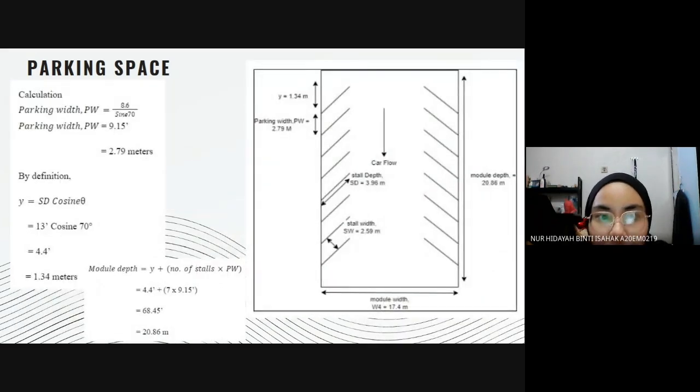Next, for the layout, the parking lot is designed with a double loaded layout, meaning that parking spots are arranged on both sides of a central aisle. This configuration enhances space efficiency by allowing more cars to be parked within a given area. The central aisle is wide enough to allow two-way traffic, ensuring that cars can enter and exit without difficulty. The total number of parking stalls is 7, fitting neatly within the allocated space and meeting the requirement for 13 spots, which is in the diagram.